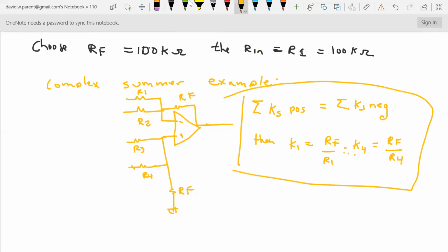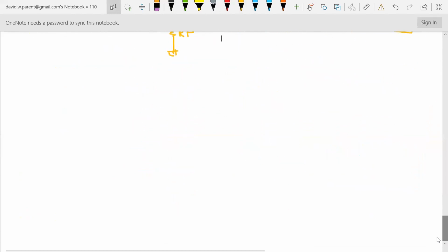On the exam, I want you to draw out the architecture, but I'm not going to ask you to calculate the R's and C's. That's a little bit much for an exam. Because sometimes you calculate it and you get a ridiculous capacitance value, or you get a ridiculous resistor value and you have to go back and redo everything. So when I'm doing those filters, the R's and the C's, I do it all in Excel. And then I check for ridiculousness.